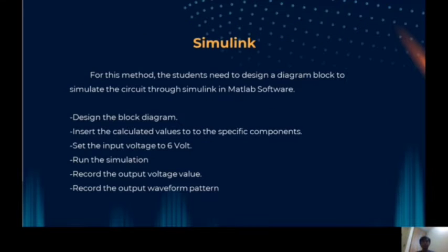The second method of this methodology is the simulation method. For this method, the students need to design a block diagram to simulate the circuit in MATLAB software. Firstly, the student needs to design the block diagram, and also insert the calculated values into the specific components and set the input voltage. When the student is done designing the block diagram, run the simulation. After running the simulation, the student must record the output voltage value and record the output waveform pattern. That's all from me. Thank you.